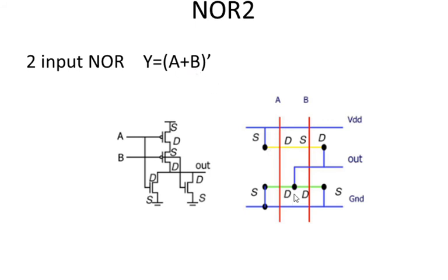So we have drawn 2 vertical lines. For any stick diagram, the horizontal lines are the same. That is, the number of horizontal lines drawn should be 4. Depending upon the number of variables, the number of vertical lines will vary.